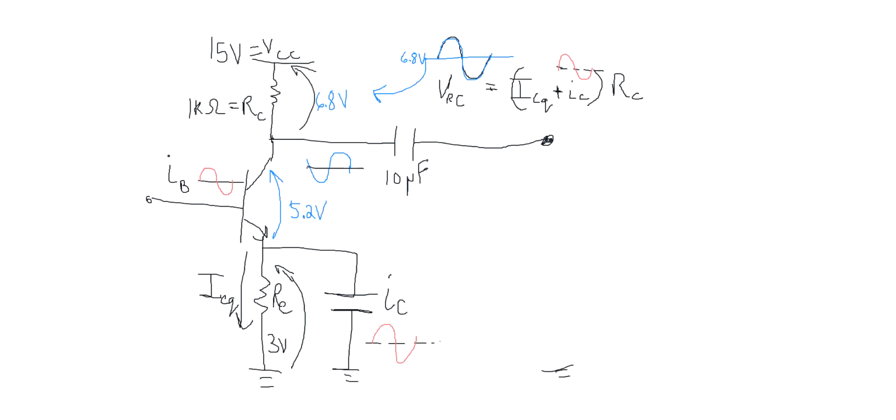So now, let's analyze this simply. We're going to rise in base current. That's going to pull more collector current. Okay, let's imagine that we actually have a rise that takes me to 0 voltage at the collector to emitter.